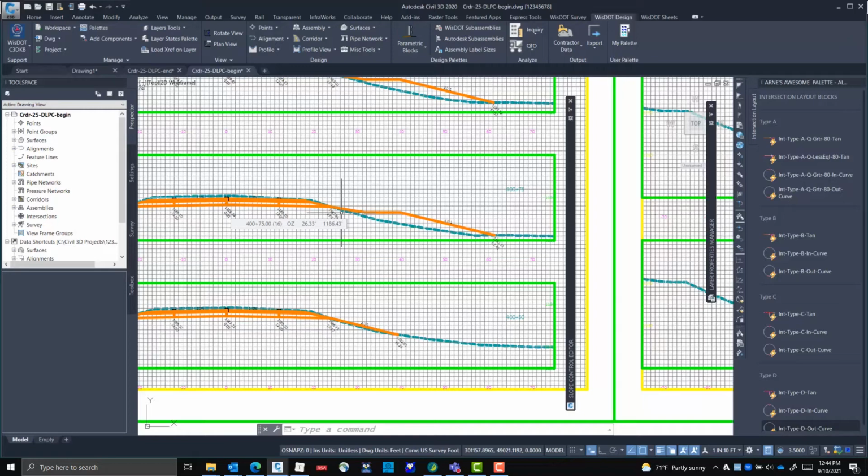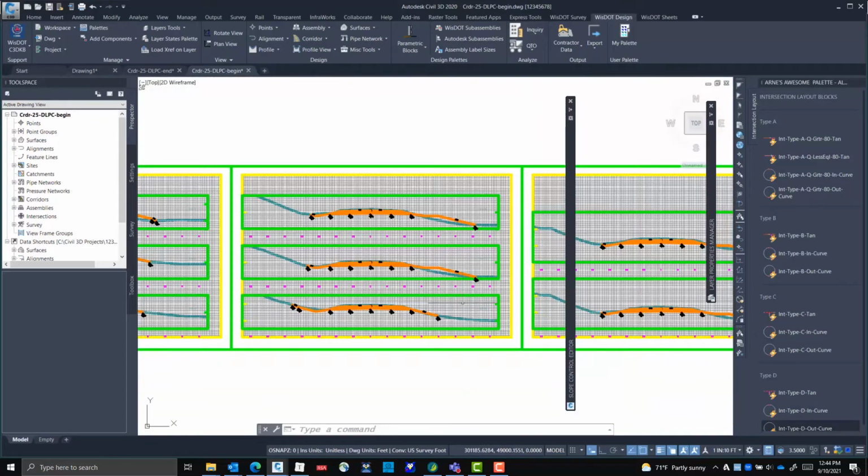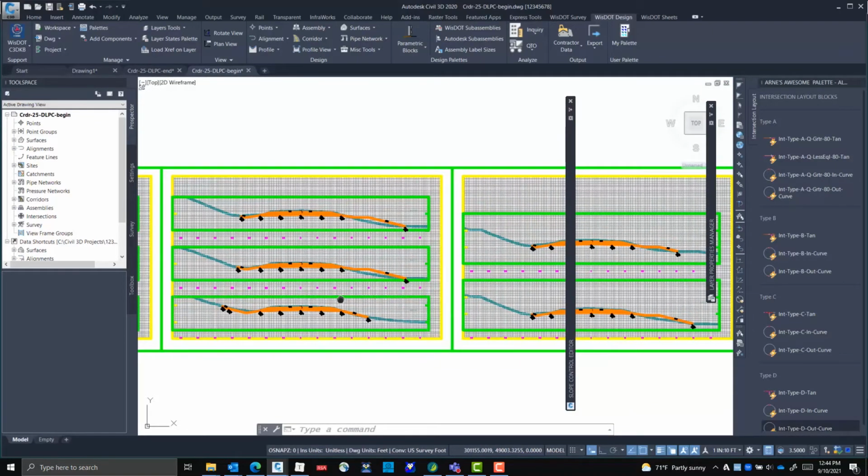Well, in ours, our first thing that we do is we don't really have cut links per se. We have what we call a ditch section. So we're always going down and cutting a ditch, and then we're going back up. And what's happening out here is we went and built our ditch, but it went up and it couldn't ever find existing. So then it bermed off and came back down and found ground. But obviously that's not what we want.